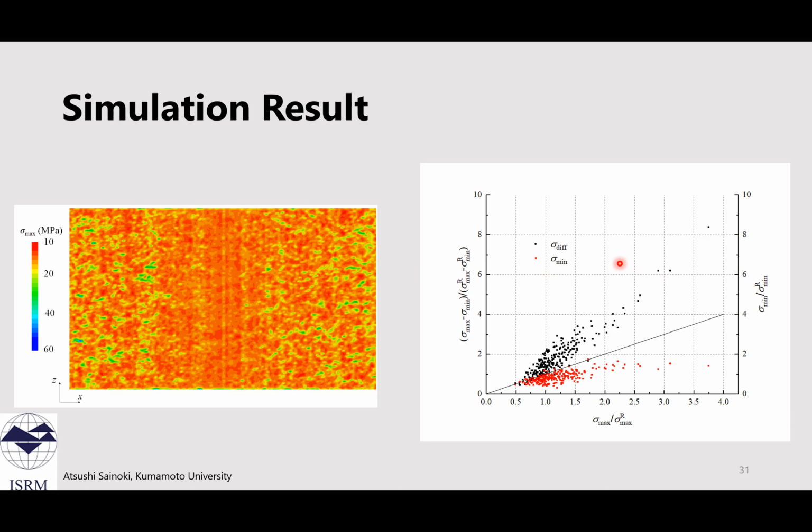And then to quantify the influence of the parameters used for the generation of fractures, a parametric study was conducted. And this result shows that the stiffness is the most influential factor. Figure C shows the influence of the normal and shear stiffnesses, which are the input parameters to compute the equivalent compliance matrix.